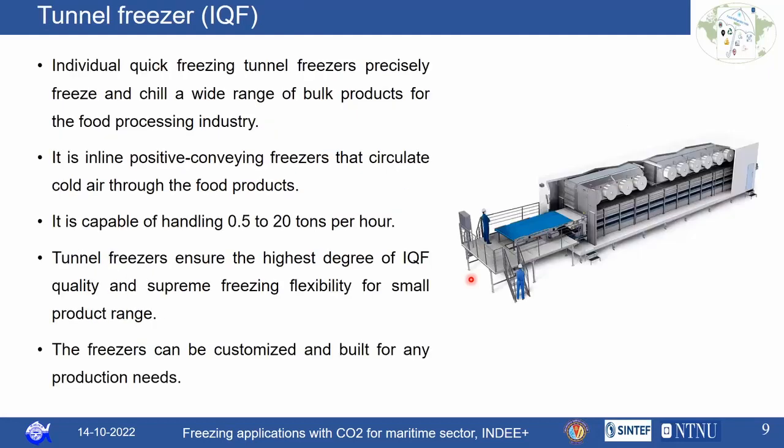Then next, another type of freezer that is mostly used is called the tunnel freezer. This tunnel freezer also supports the IQF method, that is individual quick freezing, where each and every fish product will be frozen. Here you can see the image of a tunnel freezer, where there will be the fan coils, the fan along with the evaporator coils. It can be either on the top or on the bottom, where the air will be blasted on the products that will be moving along the conveyor belt.